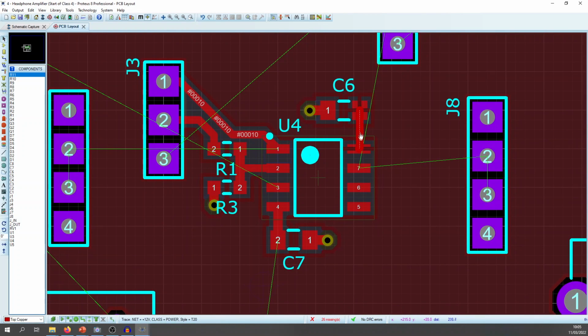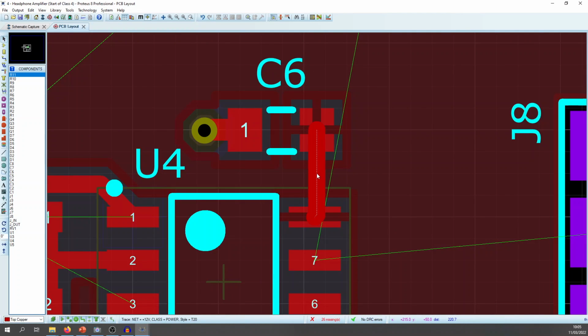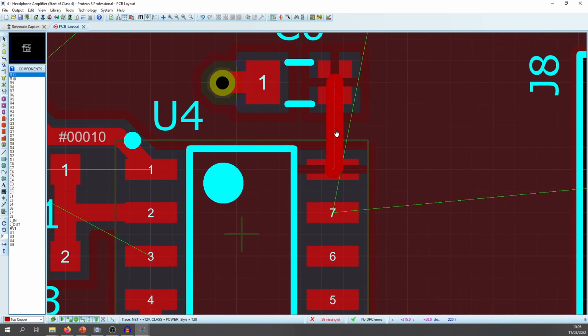These two. It's a nice thicker track. How are they joined without that track? Because surely everything on that layer isn't joined together, is it? No, but can you see this connection here, this thermal relief connection to pin 8, and pin 7 doesn't have any of that.